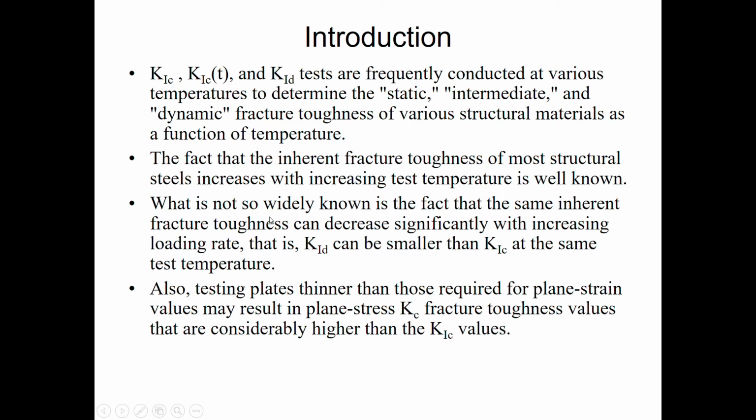What is not so widely known is the fact that the same inherent fracture toughness can decrease significantly with increasing loading rate. That is, K1D can be smaller than K1C at the same test temperature. Also, testing plates thinner than those required for plane strain values may result in plane stress Kc fracture toughness values that are considerably higher than the K1C values.